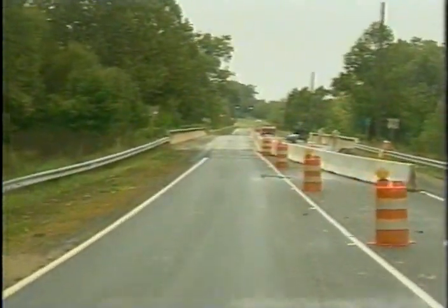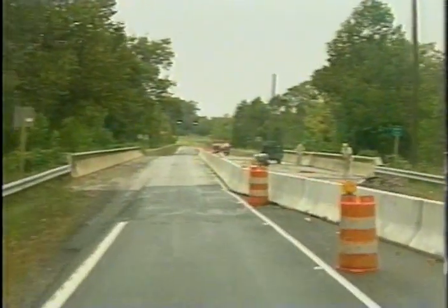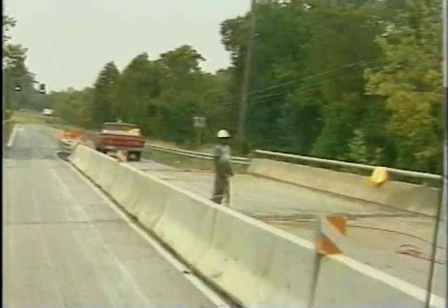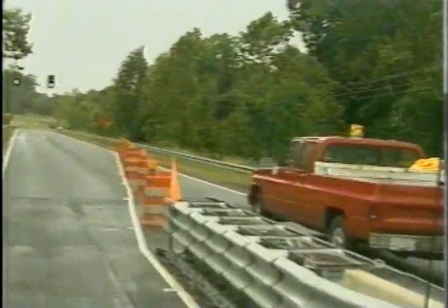The work area is the portion of a roadway where work activity is going on. It is closed to traffic and is the area set aside for workers, equipment, and materials. There are several ways to set up the work area. They include channelizing devices between the work area and the traveled way, and flags and flashing lights on work vehicles exposed to traffic. If a work area must remain overnight, it should be set up with more visible delineation.